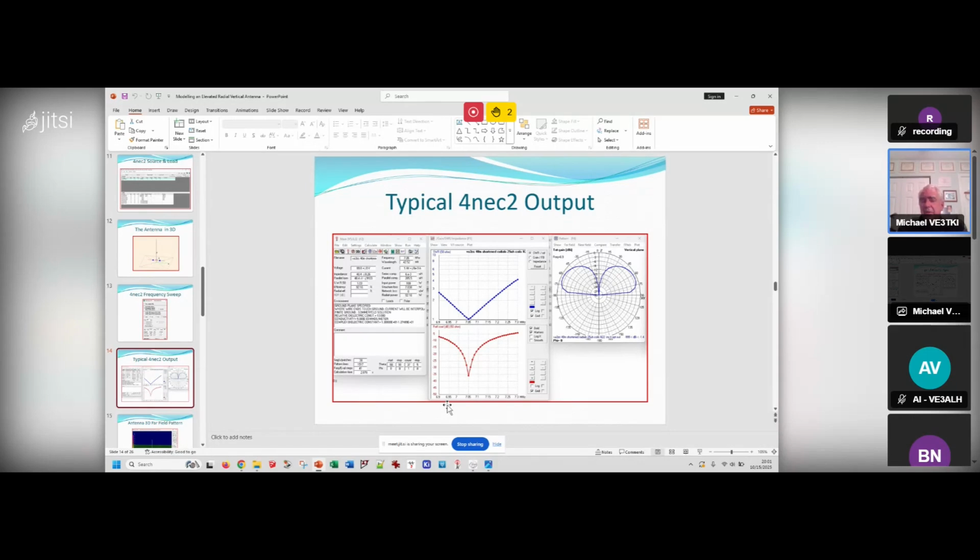I just left it. Yeah, I just wondered. That was always the part that got me, how to do the segments. But that was a good presentation. Somewhere I found, when I was looking at this, there's a formula that the segments have to be no longer than X or no shorter than X. I think it's longer. Okay. So there are some empirical rules about how to do that, I think. Well, I shudder to think what the manual looks like. So I'll take your advice and stick to 20 segments for 40 meters.